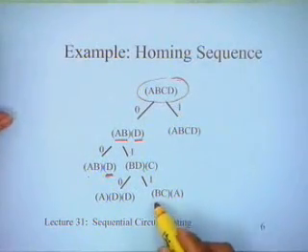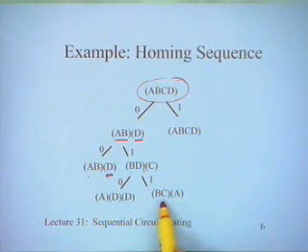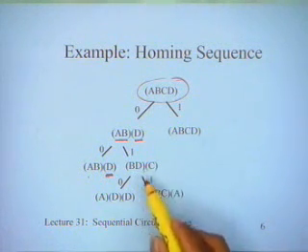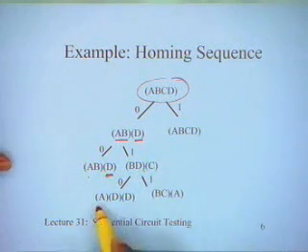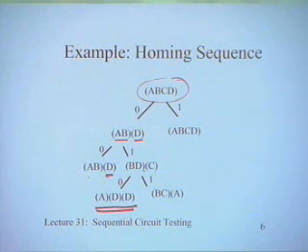Of course, one could have gone ahead, because this is still not a terminal node. The reason it is not a terminal node is that the non-homogeneous part is not the same as the previous node. But there is no need to go further, because I have reached an uncertainty vector which is acceptable to me for generating the homing sequence. I have only either trivial components or homogeneous components. All these components are just one state, or if they are more than one state, all the states are identical, so that is homogeneous.